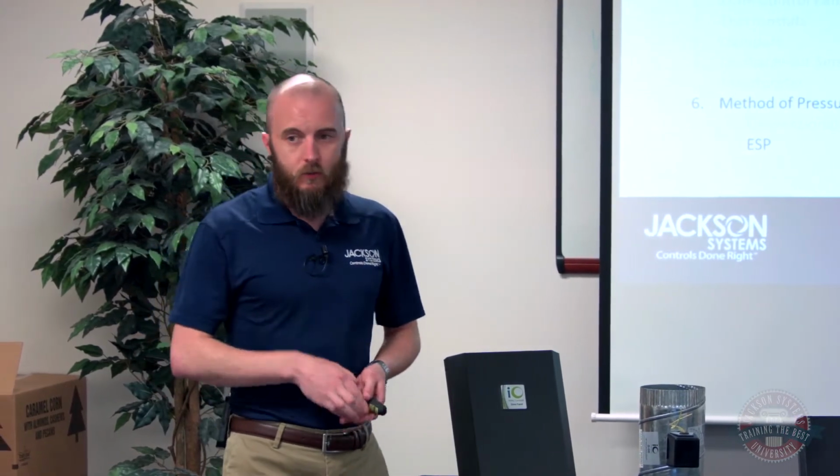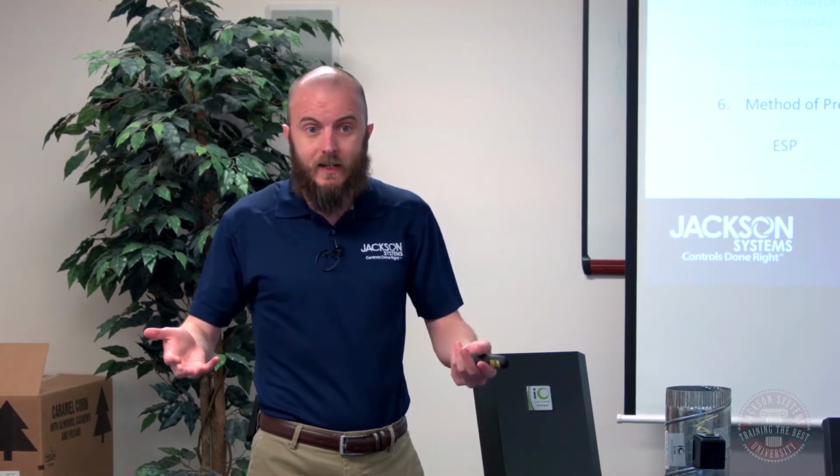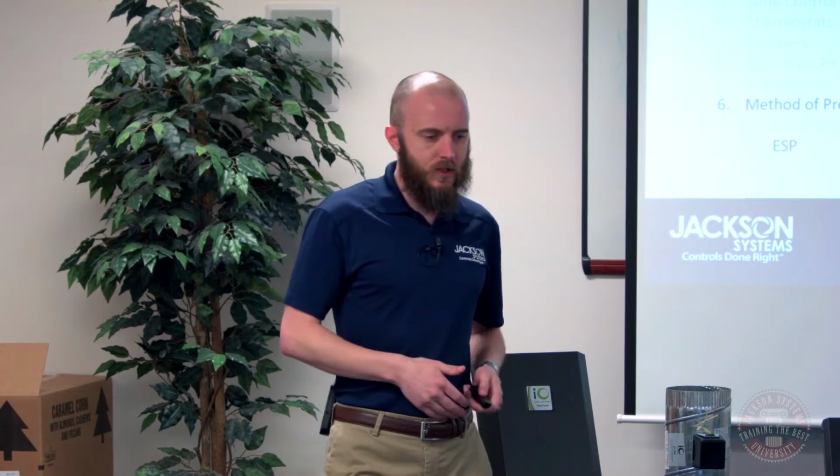But you do need to address it. You actually have to take it into consideration. If you look at it and you find, okay, I don't need to do anything special, I've got oversized ductwork, I'm going to be good with my pressures, then you're fine. But at least look at it. Don't just assume it's going to be fine.